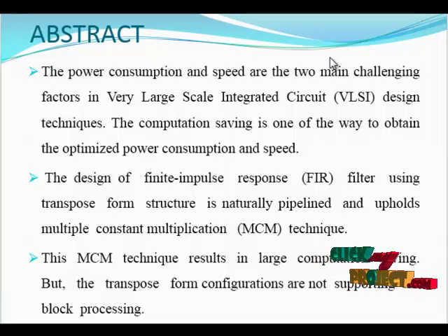There are several applications where the coefficients of FIR filters remain fixed, while in some other applications like the software defined radio channelizer, separate FIR filters of different specifications are required to extract one of the desired narrow band channels from the wideband RF front end. These FIR filters need to be implemented in a reconfigurable FIR structure to support multi-standard wireless communication.